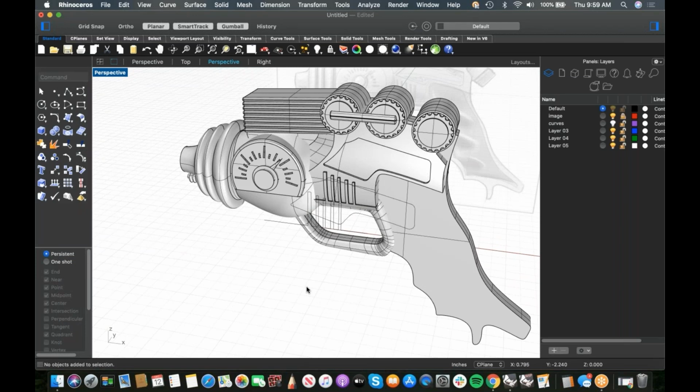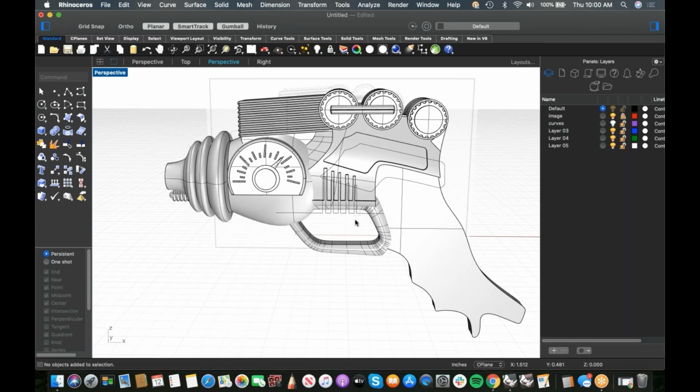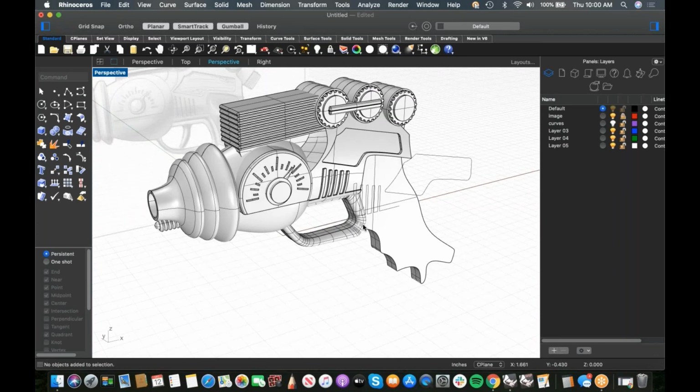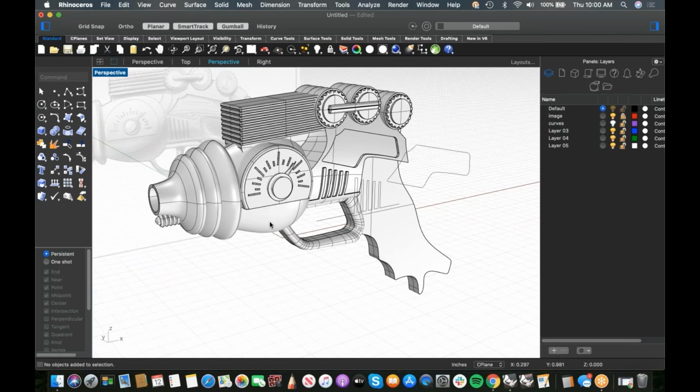And so because nothing's open at this point, I know that even if I just took this entire model as it sat without Booleaning anything together, which I do quite frequently, by the way, and just threw it to a printer, the printer will actually print each individual closed object in proximity to the other closed objects. Now it would be solid, and sometimes the printer guys get upset with you because you use a ton of resin like that. It wouldn't be shelled. But if you were using like a Z-Corp printer or something just to do a fit check, you could throw this through the printer completely unjoined or completely unbooleaned. As long as each particular element was closed, when you mesh it, it'll go through the printer just fine.